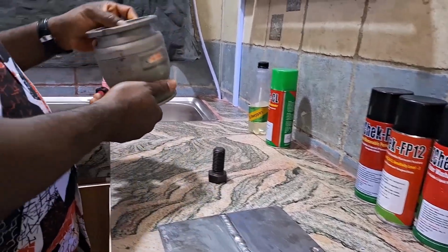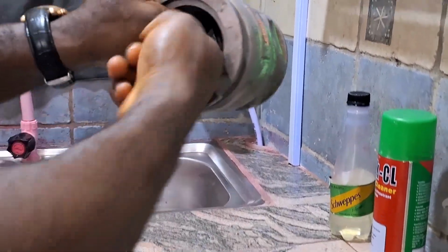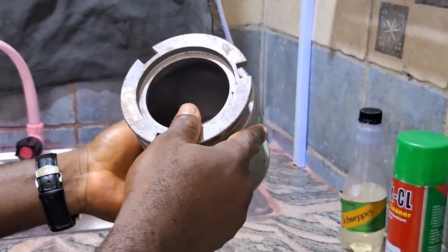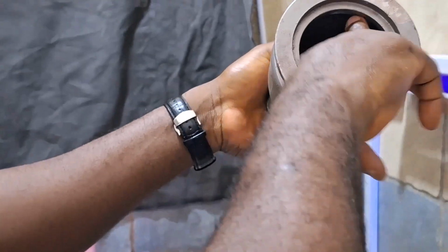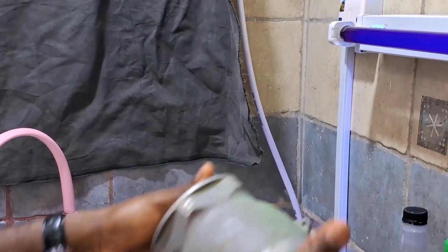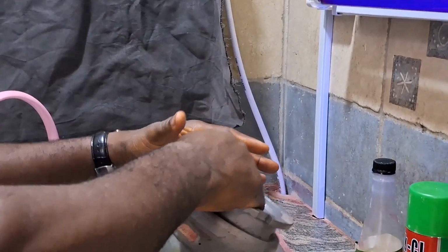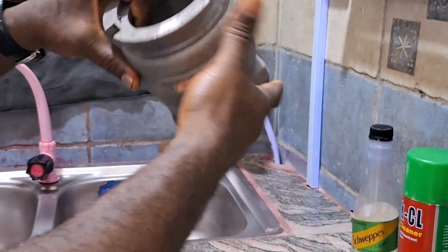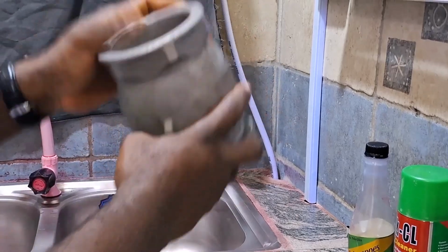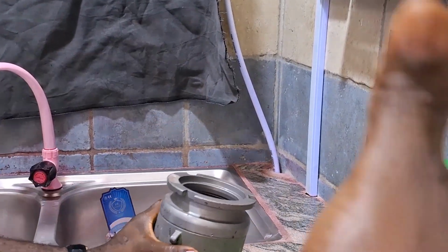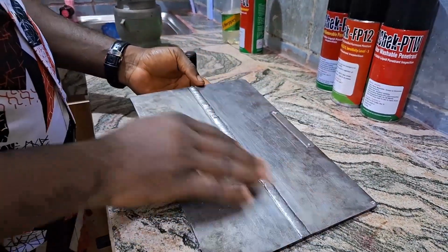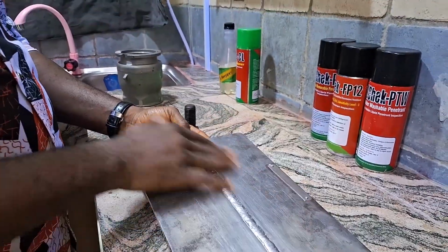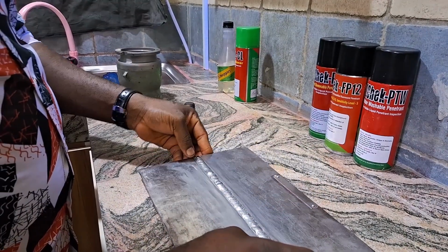If you look at this item that is very intricate, trying to squeeze a rag into these edges for cleaning is normally going to be very difficult, especially if you want to really view the internals and perform tests on the internals. So for something like this, you can put it into an ultrasonic cleaner and leave it for some time. All the dirt will come out. You can also use your vapor degreasing on this to clean. But for a plate like this that gives you easy access, you can use your manual cleaning method using your chemical cleaner to do your cleaning.